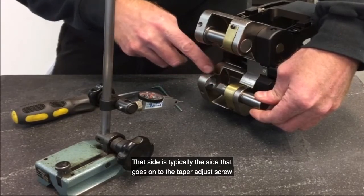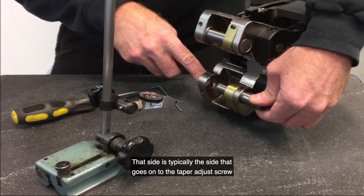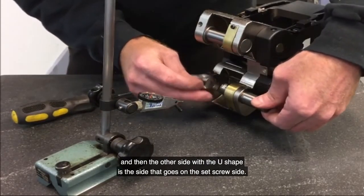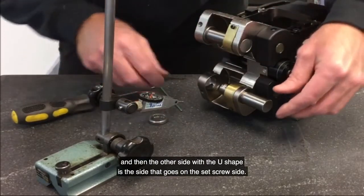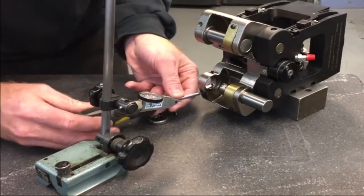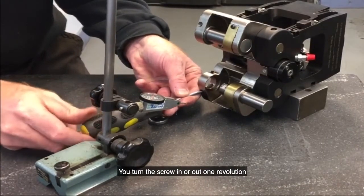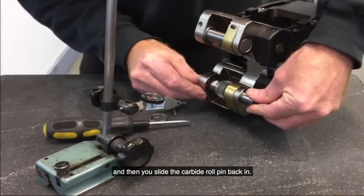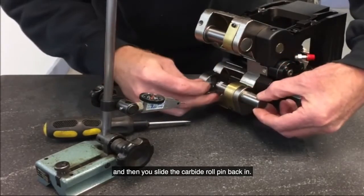That side is typically the side that goes onto the taper adjust screw, and then the other side with the U shape is the side that goes on the set screw side. You turn the screw in or out one revolution, and then you slide the carbide roll pin back in.